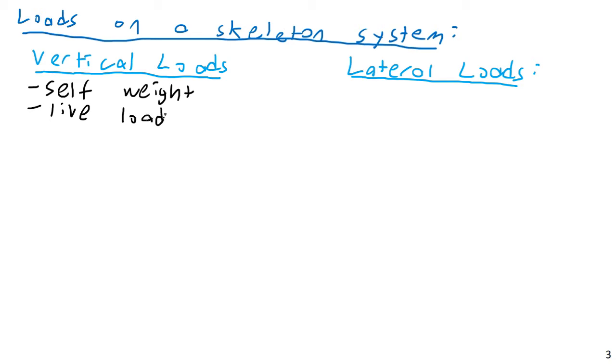When we say a live load, we're talking about anything that can move within a structure: furniture, people, sometimes walls if they can move through the structure's life. Then there are dead loads that do not include the structure's own self-weight, things like permanent pieces of equipment, permanent pieces of machinery, permanent walls that aren't part of the load-bearing system. All of those are dead loads. Then you also have things like snow load, wind, roof uplift, etc. Roof wind loads.